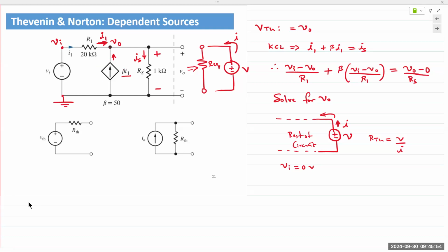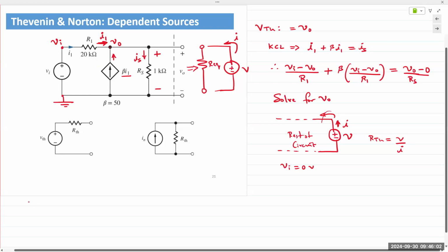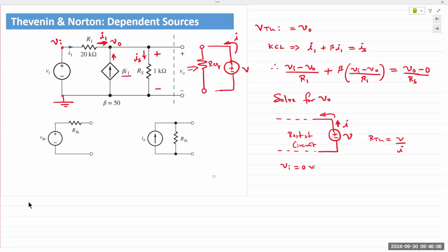So in those instances, we would need to find Thevenin voltage, Norton current, apply Ohm's law, or we can do as shown here, connect a voltage source at the output terminals, find the total current supplied by the voltage source, and apply Ohm's law that way. Make sense? Ring a bell from 113. Anyone, any questions?